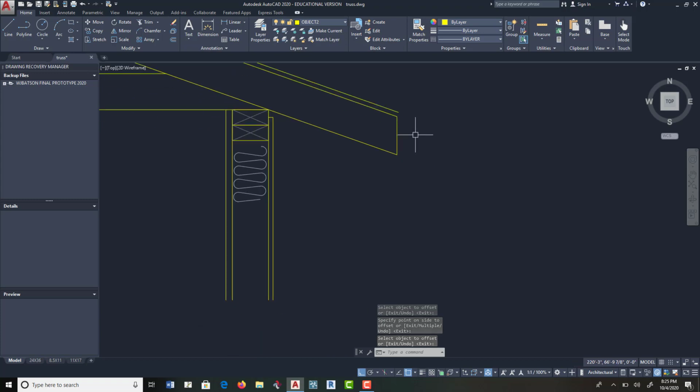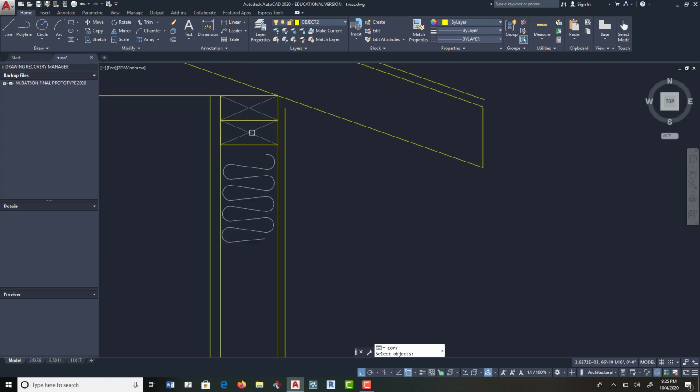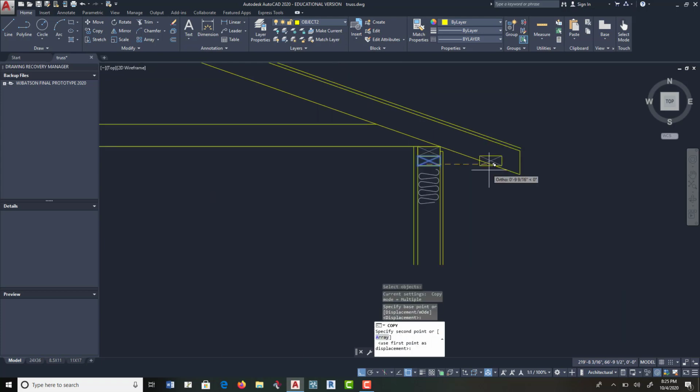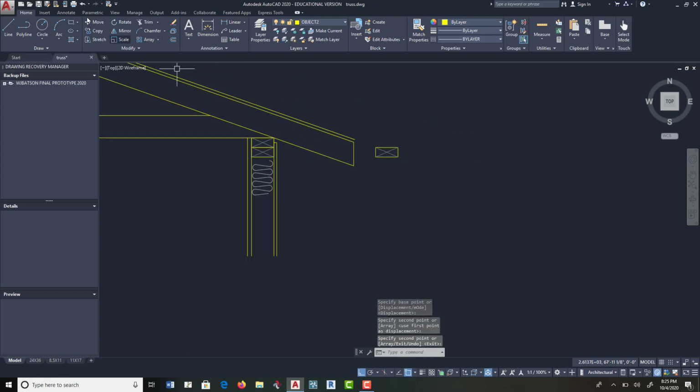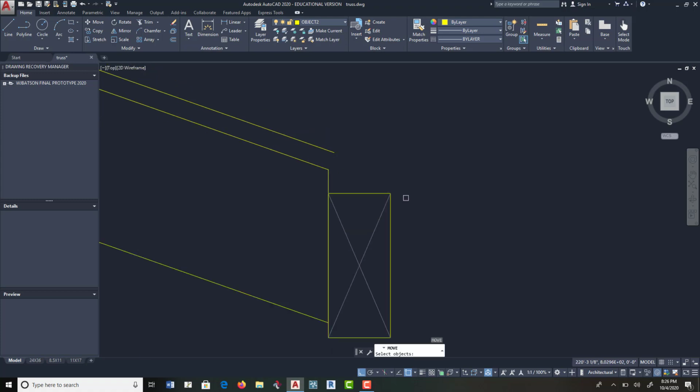And there's a soffit right there, and it's a 2x4, so let's just copy one of these 2x4s without drawing it again, and we'll just rotate it. So then we're going to rotate this. Okay, there you go. And we're going to move it against this piece here. But the sheathing has to go down and eclipse it just a little bit.